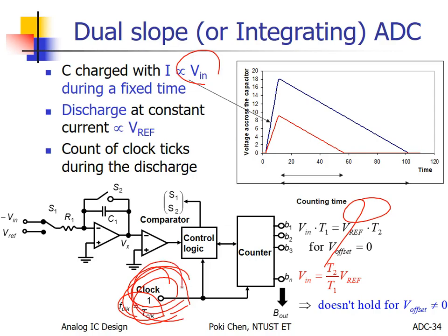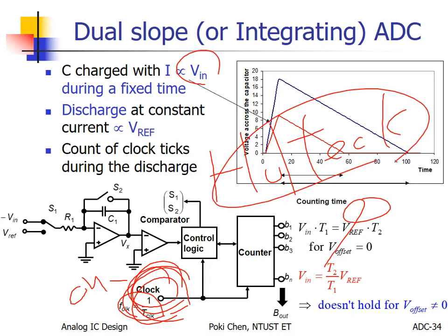But anyway, if you would like to apply some kind of on-chip oscillator for money saving, right now, according to Holtek, to my memory, for their last two visits, they told me that for such an on-chip oscillator, the accuracy may be 1% after calibration.